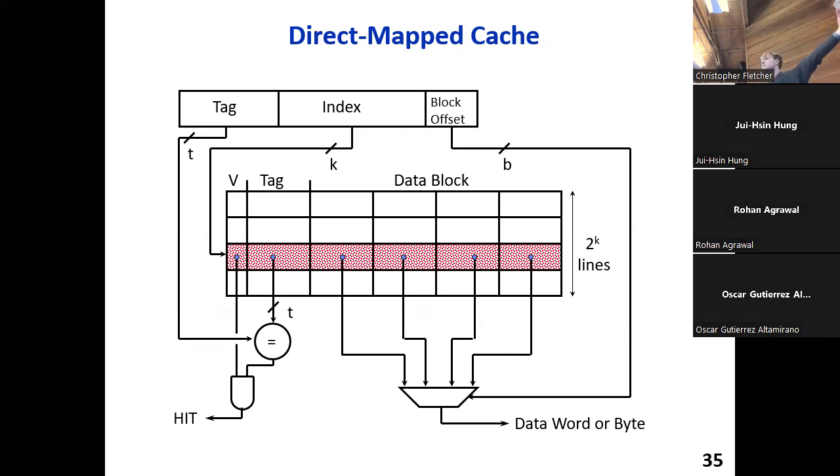And because this is a direct mapped cache, we have one slot per bin. The slot is here, the key is stored there, the value is stored there, and because we're storing a cache line as opposed to a single word, there are multiple elements there that we read out, and based on the block offset, we're going to, via a multiplexer and the select function, just like a column decoder, pick the actual word in the cache line that we need out. So this is a direct mapped cache.